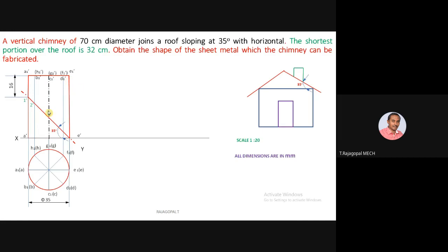Before that, what I left is you have to identify the cutting points of the section plane. So A1 dash, A dash. This is the first cutting point. Make it 1 dash. Next BB1. Always check from your top view. BB1, this is 2 dash. Next is CC1, 3 dash. It is in order. No need to worry about it. DD1, 4 dash, 5 dash. Once again, what about F1F? This is F1F. It is exactly on DD1. So make it 6 dash. On DD1, it is exactly on CC1. On this 3 dash point, make it 7 dash.